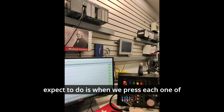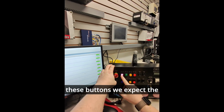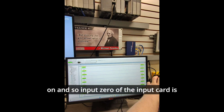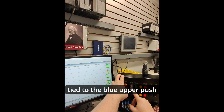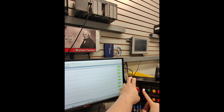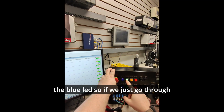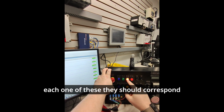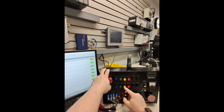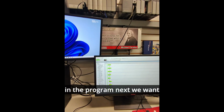The next thing we would expect is that when we press each one of these buttons, the corresponding light turns on. So input 0 of the input card is tied to the blue upper push button, which is energizing channel 0 of the output card, which is the blue LED. If we just go through each one of these, they should correspond with the input and output configuration in the program.